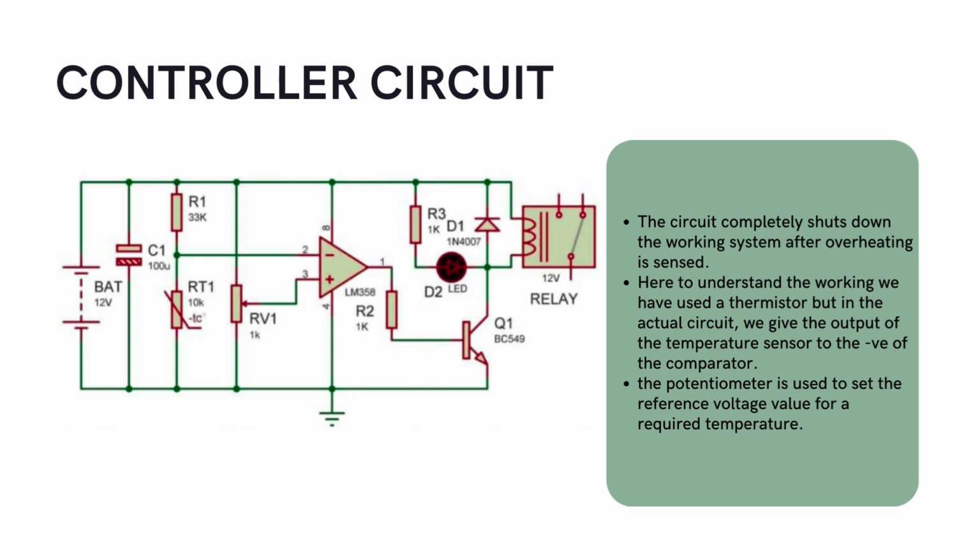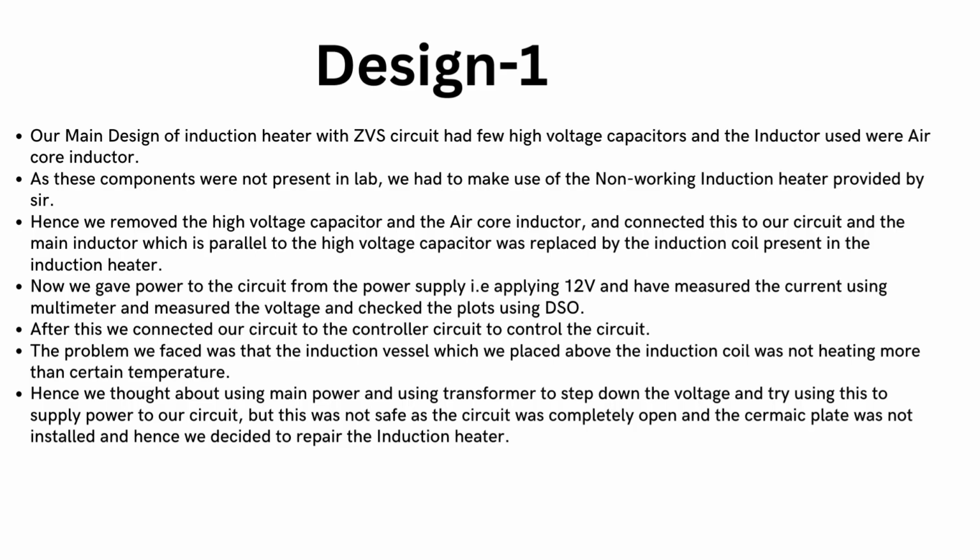So this is the circuit of only the controller circuit. When we are integrating it with the heating circuit, we thought instead of the thermistor, we'll use a temperature sensor and give it as feedback, as input to the negative terminal of the LM358. So moving forward to the hardware implementation of our circuit.